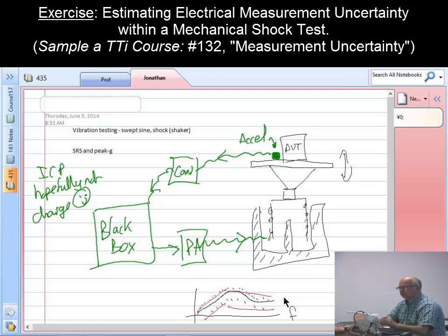You will have alarm lines which are set more conservatively, let's say at plus or minus 1.5 dB of the actual environment, and then we'll have abort lines which are set at plus or minus 3 or 6 dB. Can I just jump in for a second, John? Sure. Remember when I was talking about control charts, I said depending on the system, if it's automated, you can have the warning lines, and then the alarms go off and everything shuts down. On these controllers, as they're doing a sweep, there's a line beyond the alarm line. Alarm or abort lines? Abort line, okay. If the signal hits that, it automatically shuts the system down.